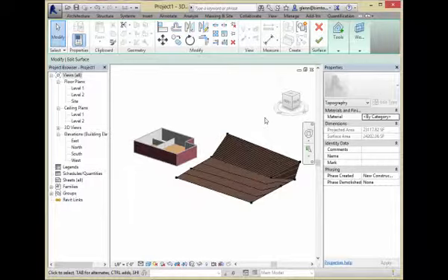Okay, next question. How do you actually break that up into different surfaces? It is kind of a good question. You could go ahead and put some floor on top of this, or some ramp on top of it. It's kind of hard to actually do because it's hard to match the topography exactly. So if you would build it like a concrete walk that would actually have a smooth elevation, model it as a floor, put something on top. But if it's really more like a path, it's going to be made of gravel or something like that, we can subdivide this into different materials. Let's show you how that works.